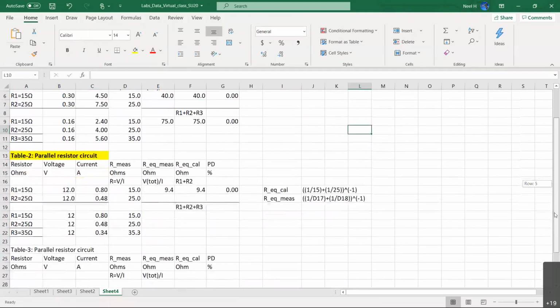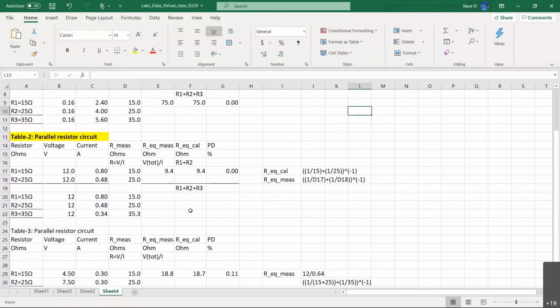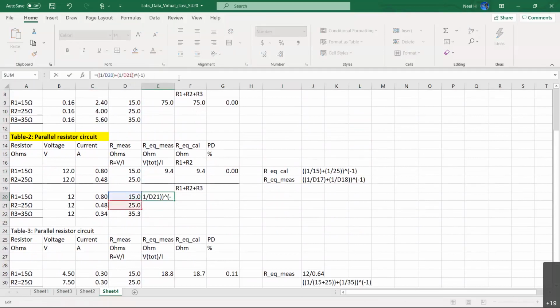Yes, correct. Yeah, that's right. So when you do actually this one, you can consider this is known. Because of that, you need to do another inverse addition of the last one. Yeah, you can do it that way, or you can copy paste this one directly here to this one, and then you go here and then do another addition of the other cell plus another new parenthesis 1 over third cell, and then close that parenthesis, then hit enter.